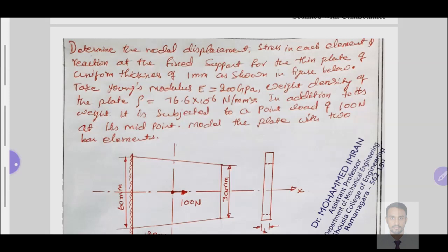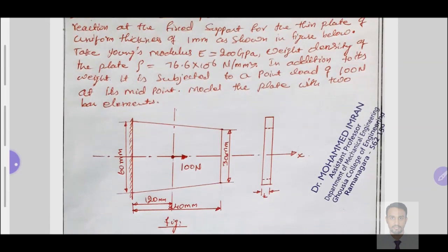Similarly, the normal force with the self weight, both the forces we need to add, then we will get a global force vector. Normally, what we consider is an applied load at node number 1, node number 2, node number 3. If a node is fixed, it is 0. For the applied load, the given loads F2 and F3, we solve the problem based on the boundary conditions, eliminating the rows and columns by using the elimination method. Then we'll get a displacement at the free end with the force. So now similarly here we have an addition to that force, the density self weight.